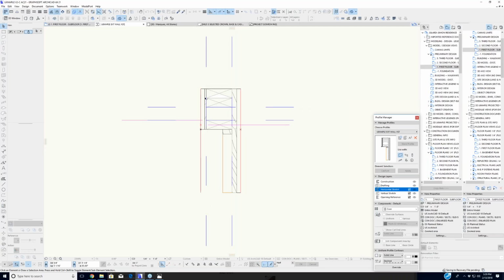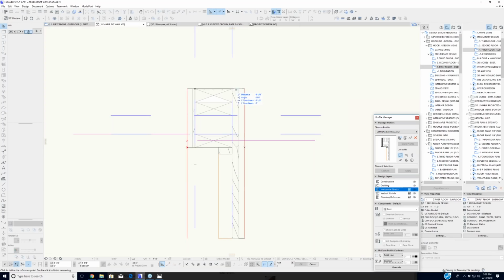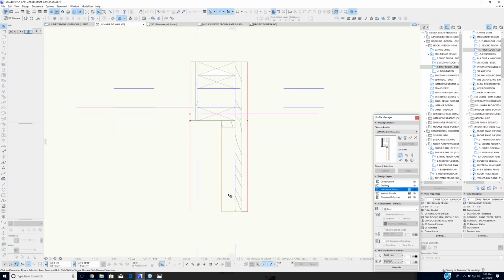Plaster, lath, meaning the wood lath, skip lath, a 2x4 wall. This measured 4 1/8, odd dimension, but they were hand cut in 1871. This would have been a rough sawn 2x material in the basement. Now that was open to the eye, so I could walk through the basement and truly measure what this was.